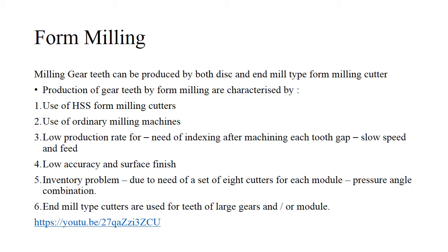If you know about the milling process, you know that indexing is very much needed. It is required after every tooth gap, because of which there is slow speed in manufacturing and low feed as well. There is also low accuracy and surface finish.